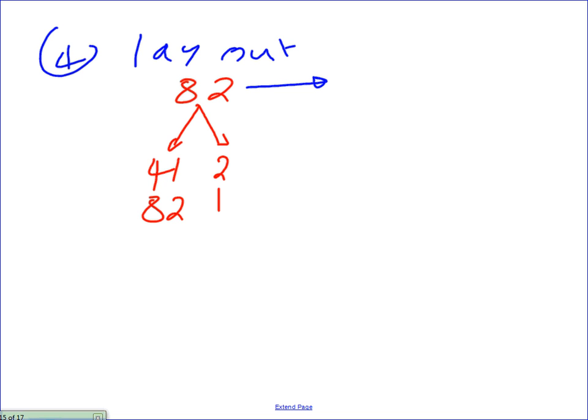That's, again, opinion. I'm going to drop one fixture here and make it 81. Now, why 81? What are the two largest numbers you multiply by each other to get 81? 9 by 9, perfect distribution. I have 9 rows and 9 columns. In return, I lost one fixture. Who cares? It's all approximation. One fixture in 82 is not a big deal, guys. Remember, we're doing it by hand approximation. I didn't go 83 because 83 would make it even worse.